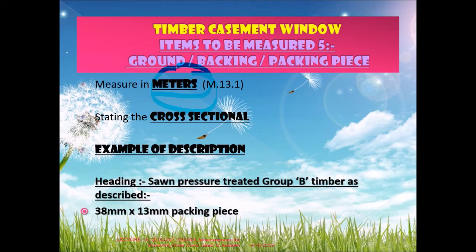The same second fixing: skirting, picture rail, the rail and the light. This is under the same category, but because this one is behind the framing, normally we do not use rod pressure treated timber. We normally use sawn timber. That is sufficient. Sawn timber, what is the size, and then for what purposes?